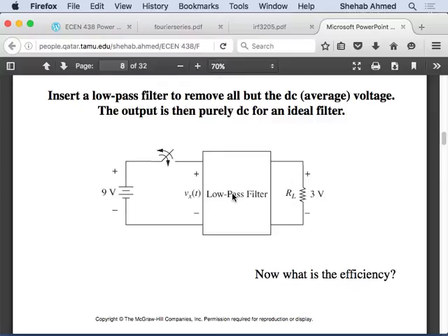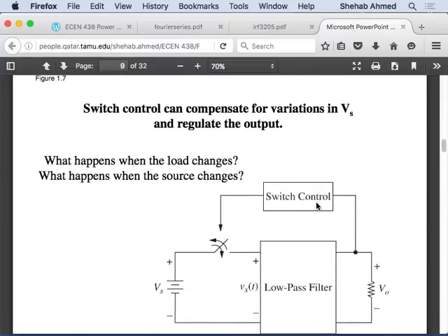But then you cannot increase the voltage too high, because this is a device you're holding in your hand, right? You cannot hold a device in your hand that has 1,000 volts, for example, inside it. So there are many considerations. At the end of the day, there are safety issues, performance issues, size issues, cost issues, and that's what you do in power electronics. You compromise between all of those to come up with a converter. But the topology is very similar. All the topologies for the power converters are very similar.